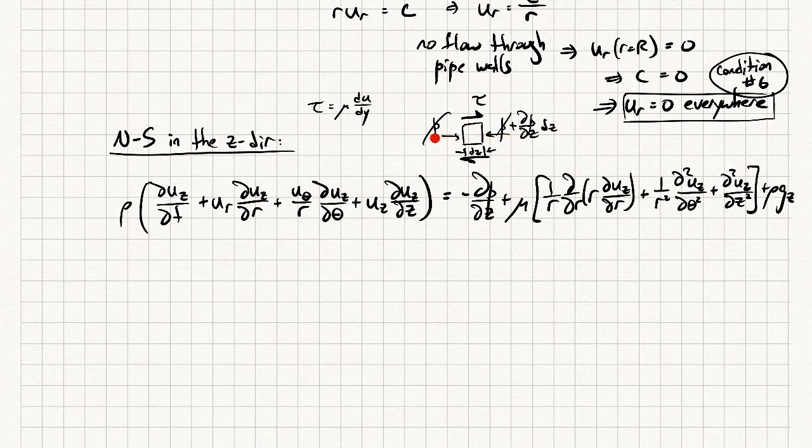But just like the pressure variation, the stresses between the top and the bottom, you might have a tau and a d tau dy here times a dy. So it's the stress gradient that will matter for the net viscous force acting on the fluid element. So there's a derivative here and then a derivative here, which results in a second order derivative, and that's why you see second order derivatives here. So this is the net viscous force per unit volume acting on a little piece of fluid.